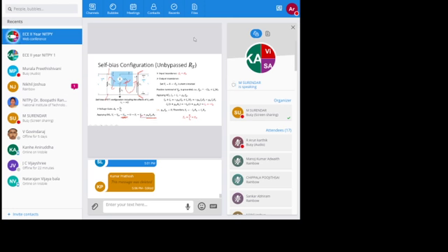V0 is equal to minus GM into VGS into RD. So we get the voltage gain as minus GM RD divided by 1 plus GM into RS. Now we want to compare. This is for unbypassed RS, that means the bypass capacitor is not connected to the self-bias circuit.